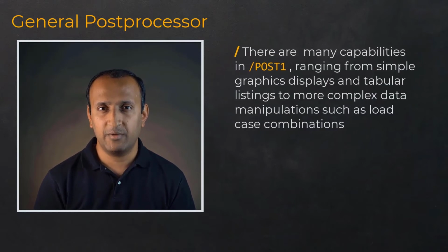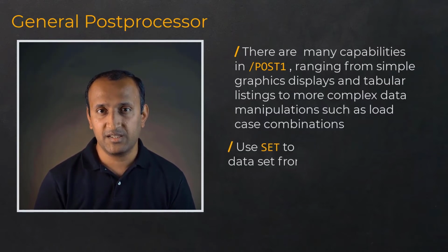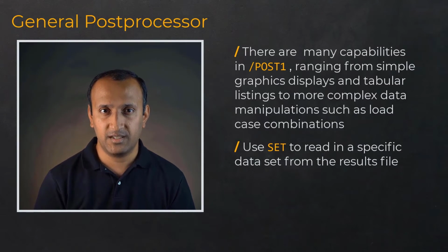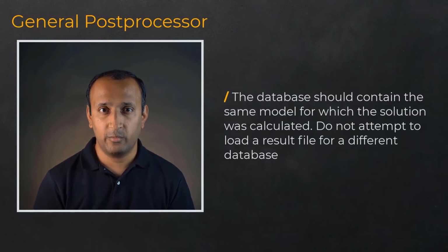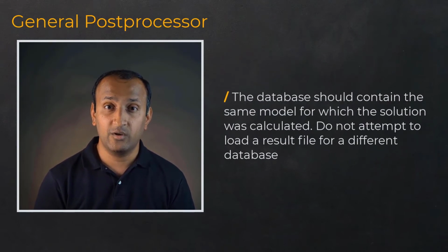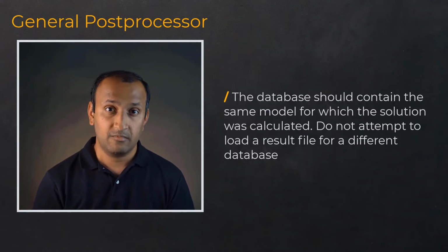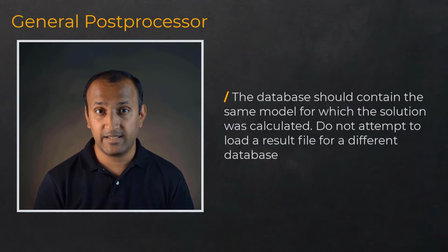POST1 has many capabilities, ranging from simple graphic displays and tabular listings to more complex data manipulations such as load case combinations. The first step in POST1 is to read data from the result file into the database with the SET command. The database should contain the same model for which the solution was calculated, including the element types, nodes, elements, real constants, material properties, and nodal coordinate systems. Otherwise, a data mismatch can occur.